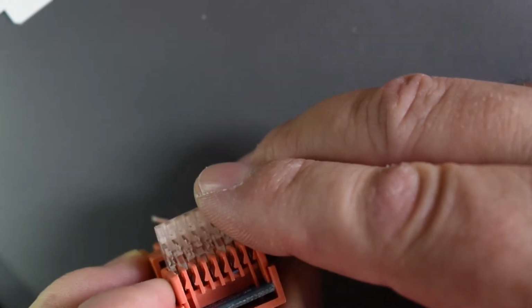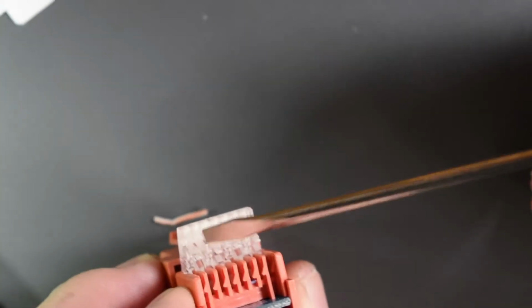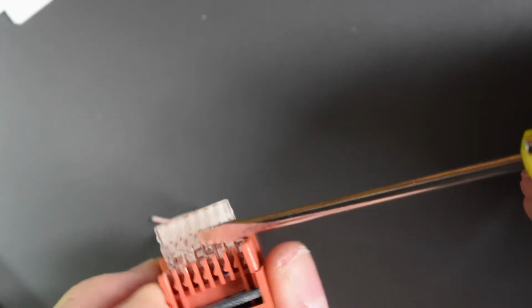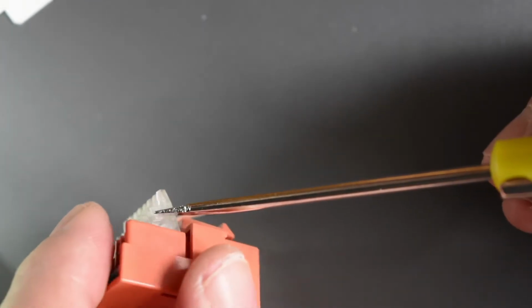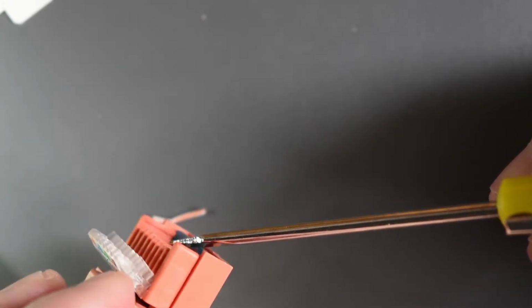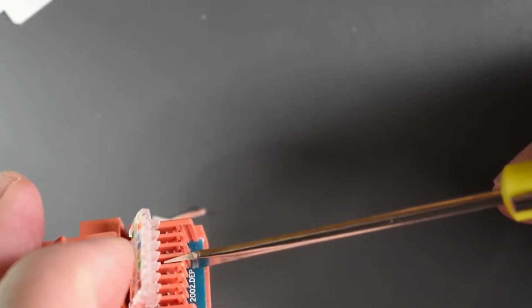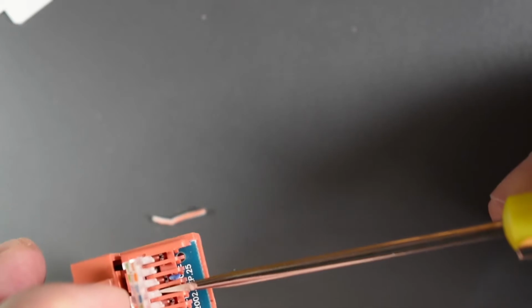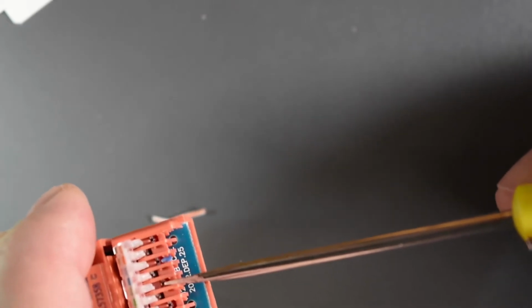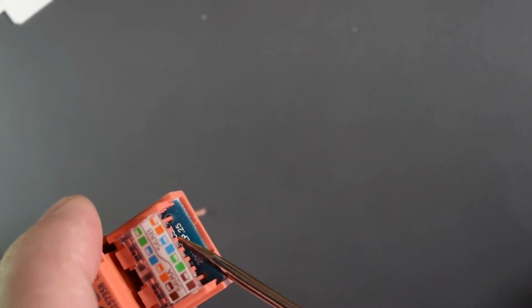You see it has those ribs here. Where's my little screwdriver here so I can point things out? There are those ribs looking like the punch down pushers. All right. Now, when you put the conductor inside the groove, you're going to use the hinge to push them down and push them into the IDC.